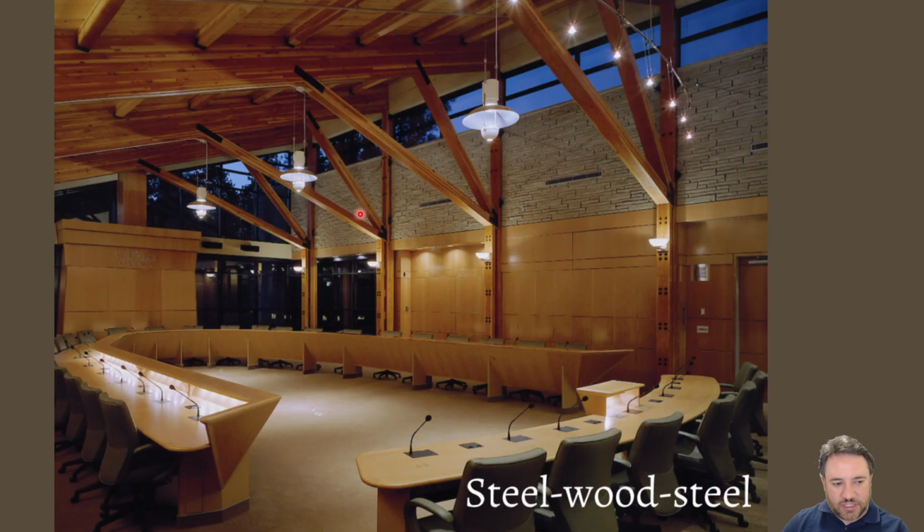The opposite of the wood, steel, wood connection is the steel, wood, steel connection. So this is basically, we have steel on the outside, the wood members on the inside, and then you'll have an identical steel member on the other side, which you can't see here. But so there's steel, wood, then steel on the other side. It's just basically clamping 2 pieces of wood together with steel plates, and then bolting those steel plates to the wood using bolts going through all three.